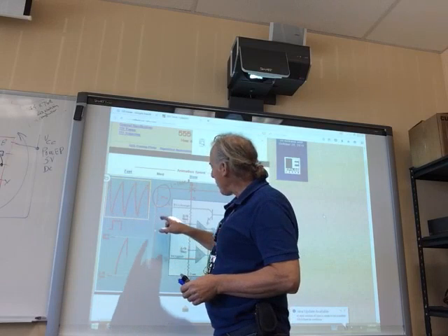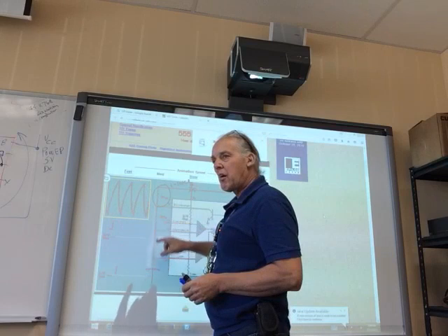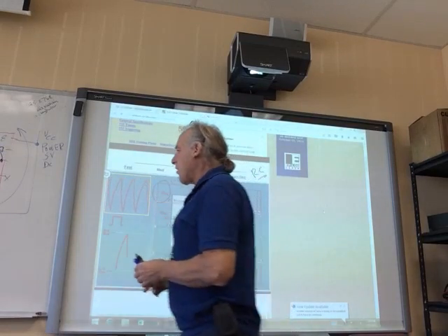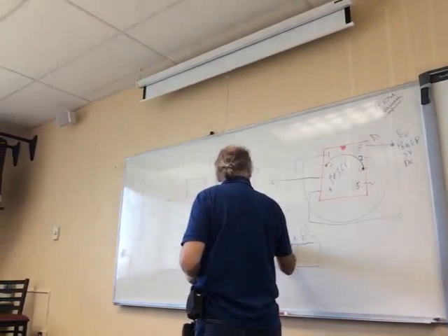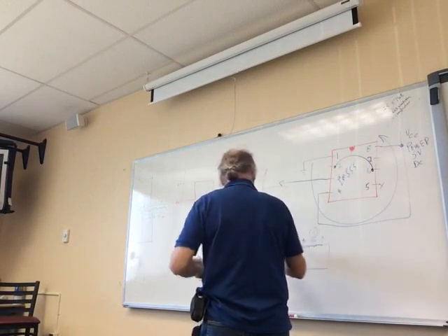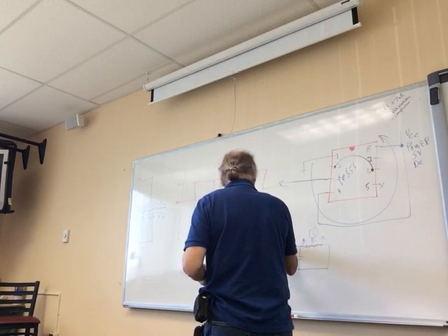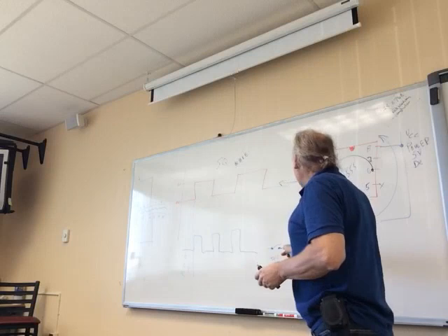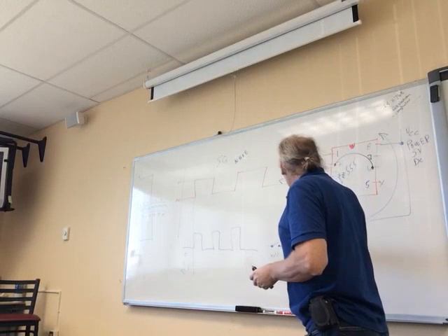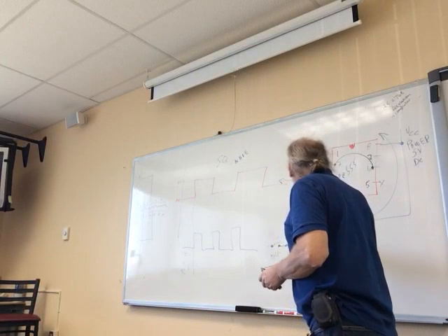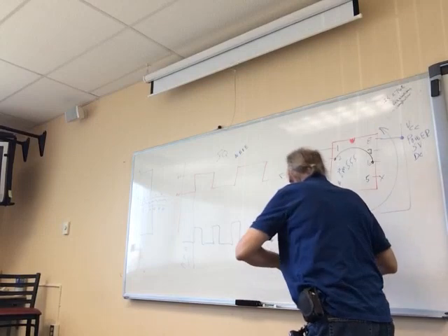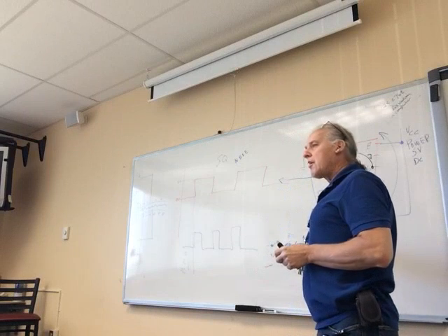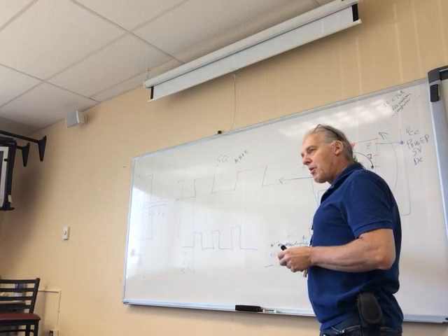Notice we have a capacitor resistor network here. Okay? You say, well, what's this? This is the resistor that actually charges that up. So it's really simple. What they did was they just said, okay, fine. If you want to be hard about it, what we'll do is we'll give it a limit resistor like this, and we'll let that charge R2. We'll let that charge up this network right here. And then we'll let this one discharge it. Okay? So we good with that?